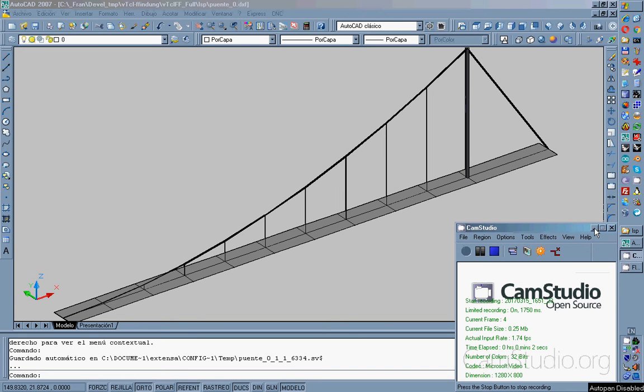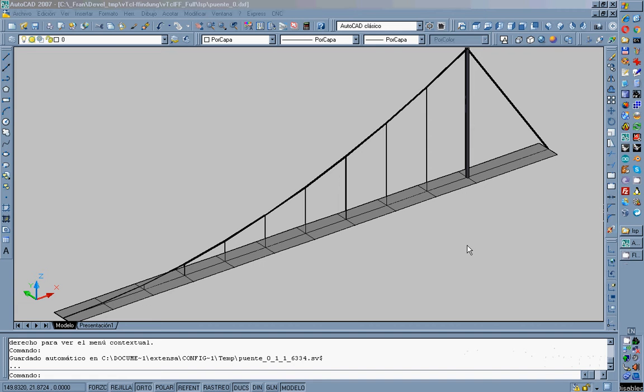Good morning. Today we are going to see AutoLISP applications. I have a program for AutoCAD to create the numbering of the structure. So now you can create the structure in AutoCAD, number all the structure in AutoCAD, export it, and then you will have almost most of the work done. The remaining thing will be to add the geometric constraints, but in this tutorial we are not going to talk about that, just the AutoLISP routines.